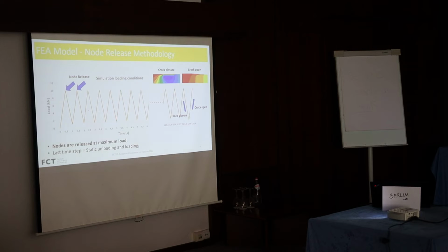In terms of the node release methodology, we use 2 different approaches. In the first cycles, the nodes are released at maximum load to obtain the plastic wake, and in the last time step, we apply loading and unloading to obtain the crack closure and the crack opening.